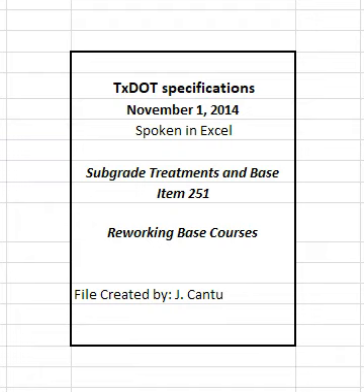4.5 Curing. Cure the finished section until the moisture content is at least 2% below optimum or as directed before applying the next successive course or prime coat. 5 Measurement. This item will be measured by the station, square yard, cubic yard, or ton. Square yard and cubic yard in original position measurement will be established by the widths and depths shown on the plans and the lengths measured in the field.